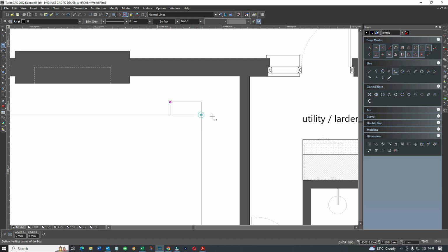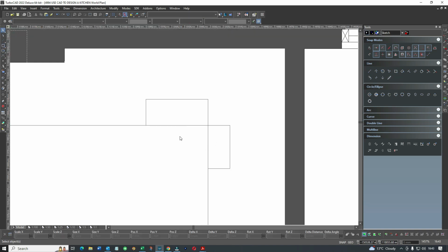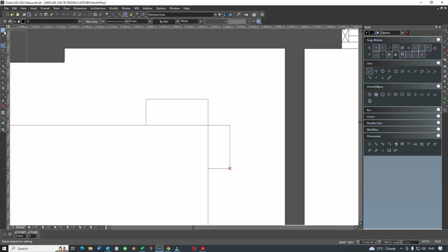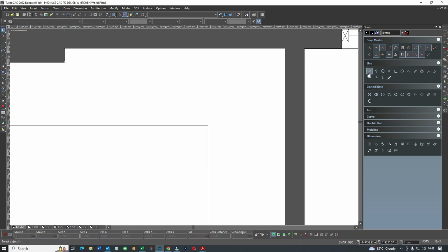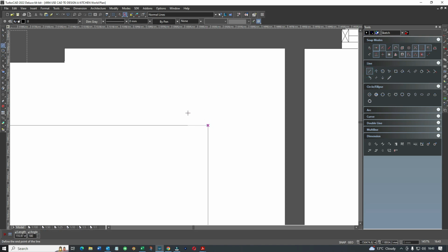Let's assume that was a corner unit and that was a corner unit. It means that when you go to open the drawers here, you're going to pick up on the drawers on this unit. So we don't want to do that. So generally they start about 30 mil out. So we're going to try 30 and see where we get with that.